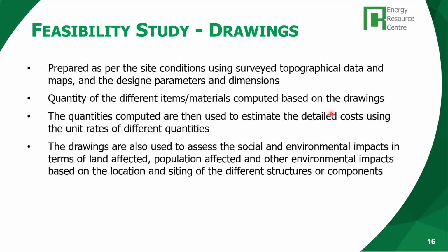This has to be shown in the drawing, and based on the drawing we can calculate these items. Then once we calculate the quantities, using the unit rates, the cost of cement, sand, aggregate, we calculate the cost of the different civil structures. Similarly for hydromechanical structures, calculating the steel, we calculate the cost.